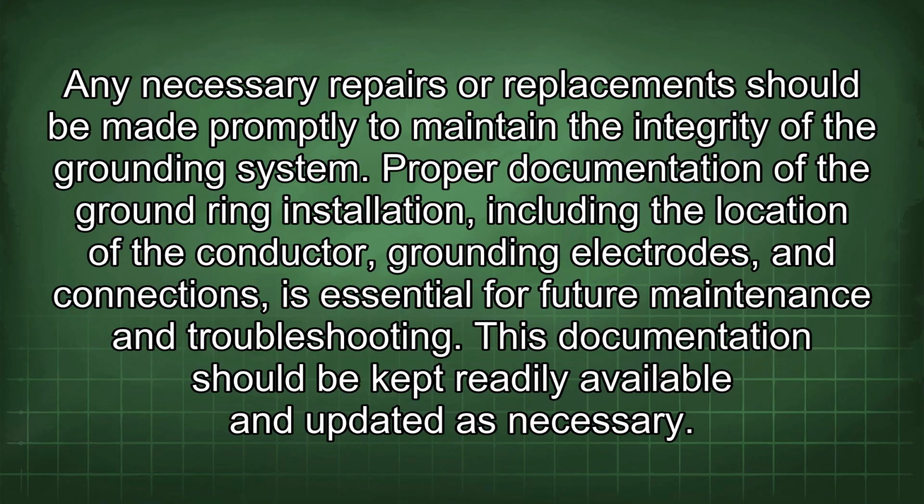Proper documentation of the ground ring installation, including the location of the conductor, grounding electrodes, and connections, is essential for future maintenance and troubleshooting. This documentation should be kept readily available and updated as necessary.